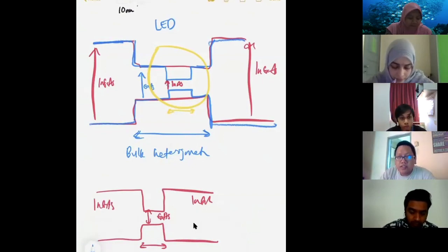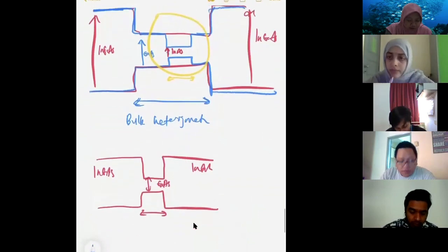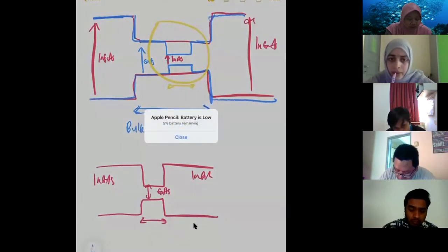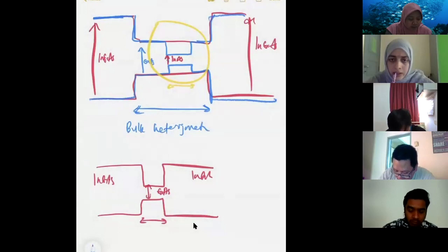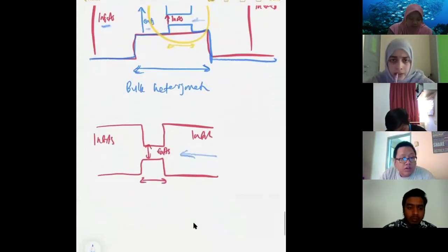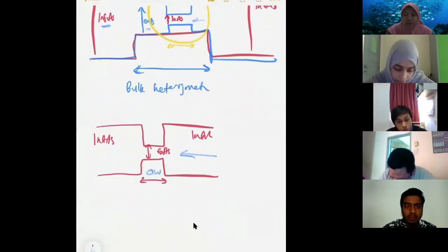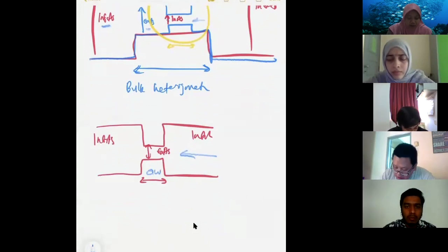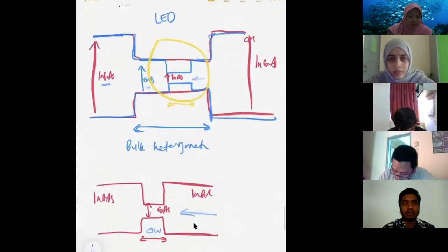Yes. Okay, so I can make a quantum well out of three materials here. The indium gallium arsenide, then the gallium arsenide sandwiched by indium arsenide. So indium arsenide is the quantum well. Or I can make it like this at the bottom here, where the quantum well is the gallium arsenide. The condition is that it must be sandwiched. It must be heterojunction. It must be sandwiched by a larger band gap material, right? And you need to be smaller than 100 nanometers.